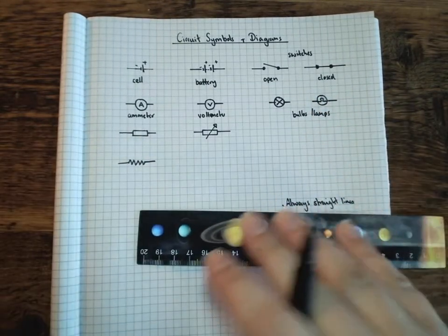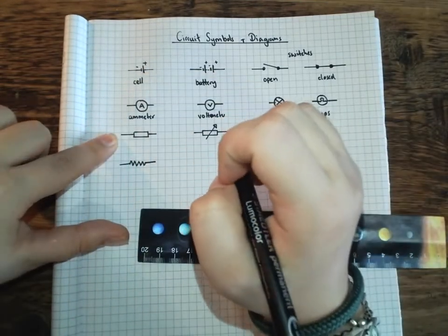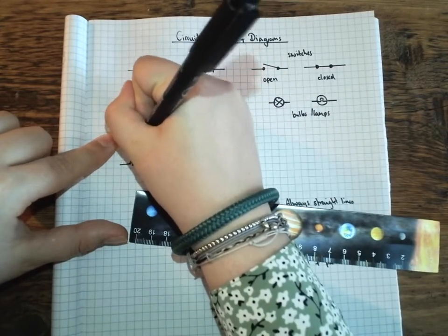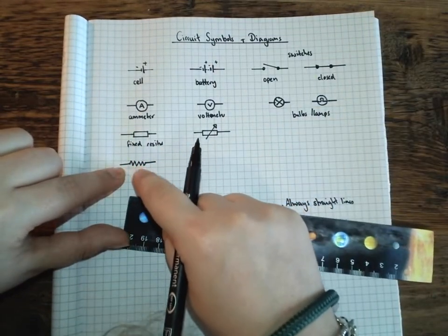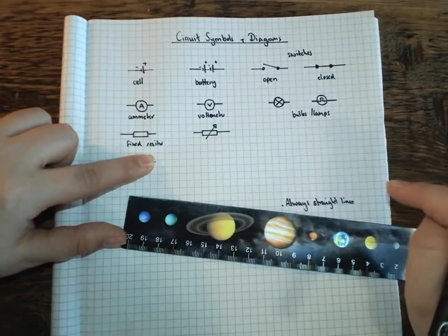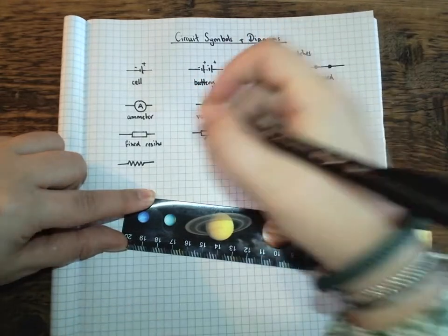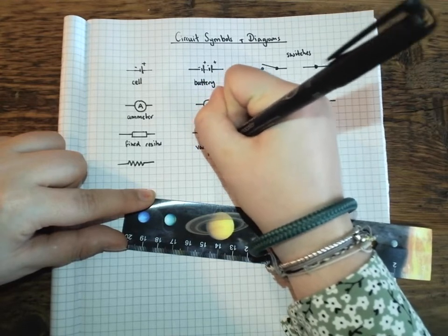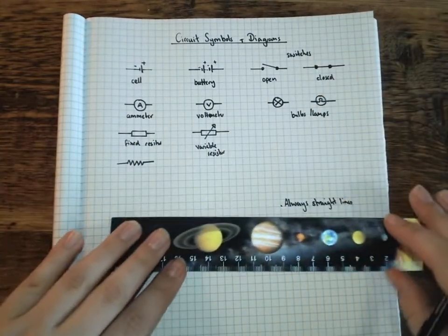The other device that we're going to be using is a resistor. We have two types of resistors: fixed resistors and variable resistors. In this case, we have a fixed resistor. That simply is just a little rectangle. Again, online you might see it represented with this little zigzag line, but I'm going to just use the rectangle for this. Or you might see that rectangle with a little line, kind of an arrow pointing through. That means that we have a variable resistor, and a variable resistor basically means we can change the resistance, we can vary the resistance there.